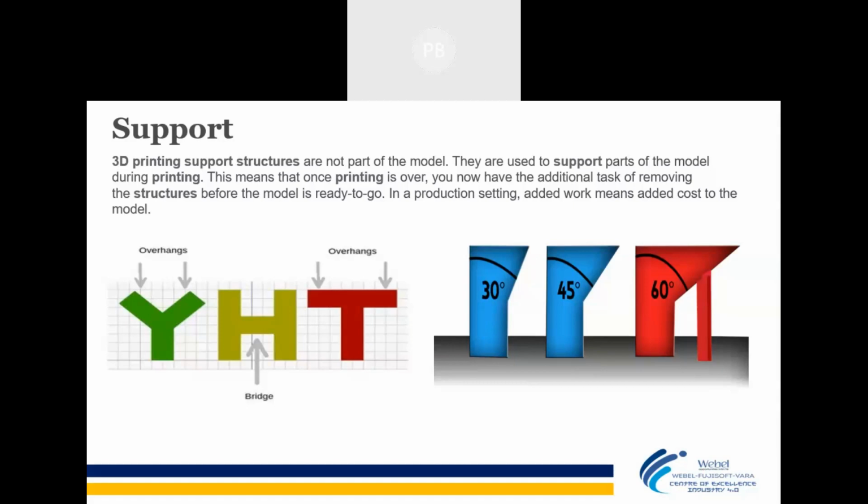Yes, sir. So this kind of thing we have to identify during printing. We have to set the printing in such an orientation so that there will be less and less support development. With minimum support development, your part will have minimum wastage. Obviously, the higher the support development, the higher the percentage of wastage.